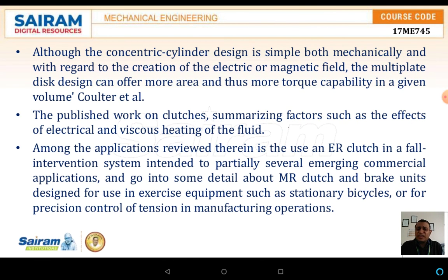Although the concentric cylinder design is simple, both mechanically and with regard to the creation of an electric as well as a magnetic field, the multiple disc design can offer more area, thus more torque capability.